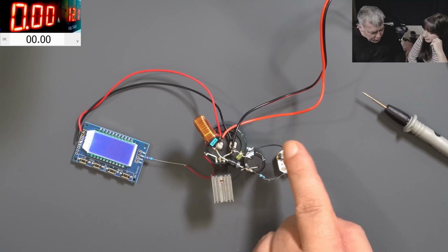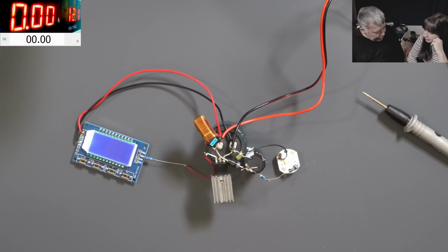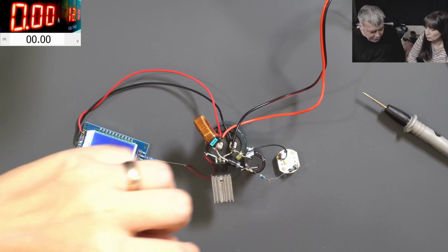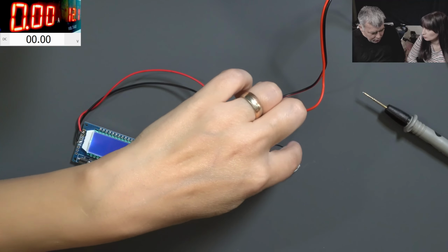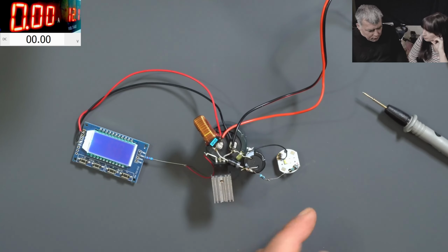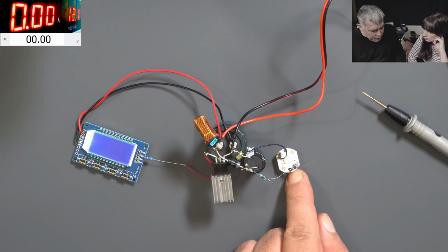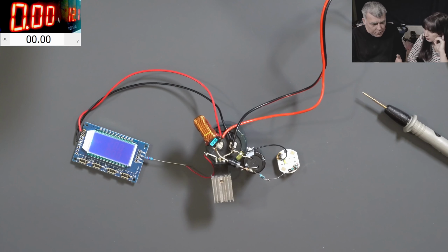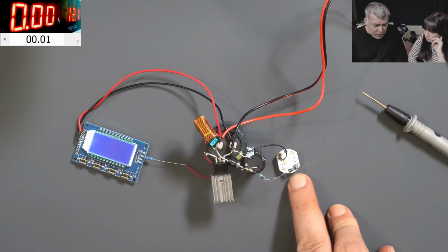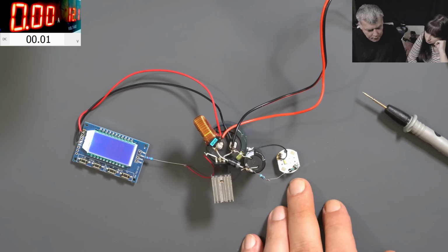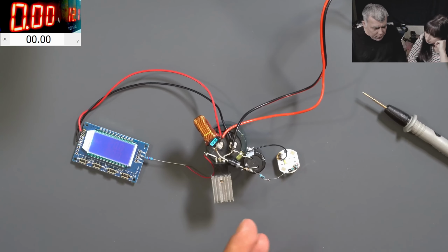Every component will take the pressure. They're in series. It's not like only the resistors get burned and the LED will be fine. It will get burned as well, right? If you pass too much current through the LED, because every LED has a certain current rating. Not this one. This one is quite a strong one. I think it can take even 2 amps. But a normal LED, like 25 milliamps, you can easily pass that current and burn the LED.